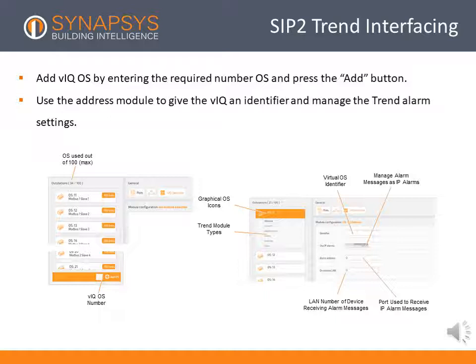Open the outstation and add a label, alarm, specifications and attributes that may be required. The next 4 headings will enable individual configuration of sensors, knobs, inputs and switches. The final option defines the users for the outstation, allowing trend security to be added.